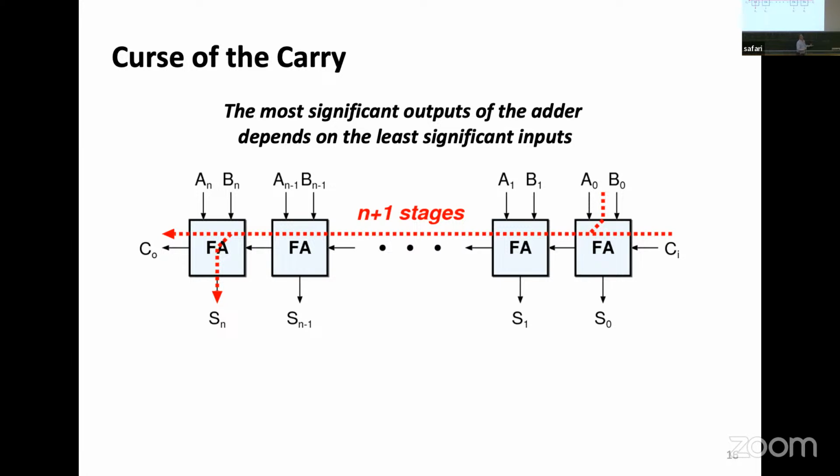Now this guy already finished his calculation. He said, I added 1 plus 0, carry was 0, so the result is 1. And now it says, hey, excuse me, there's a carry. Really? Okay, I have to work again, and now the sum will be 0, and I will send the carry over here. And the next guy, who was long gone and done, looking forward to the weekend, going home, hears, hey, excuse me, carry. He's going to change his mind and change the carry.